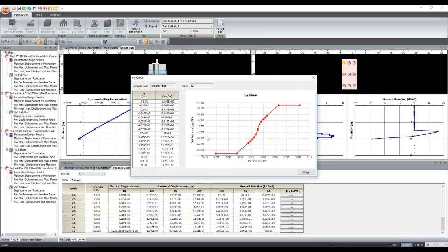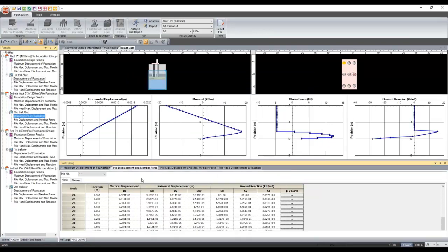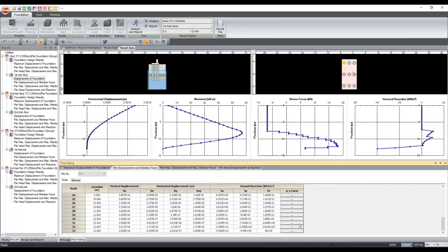So what we do is, let's say if you are going for modeling of 10 meter piles in Midas Civil, then you can copy your spring data in SOILWorks and paste it in Midas Civil. Otherwise, you can go for the 13 meter length again. And since we already generated the bottom fiber soil spring, we can even generate the top fibers and the middle fibers as well.